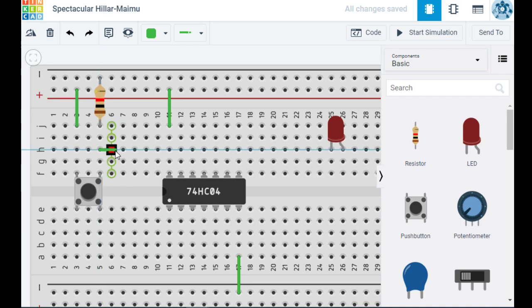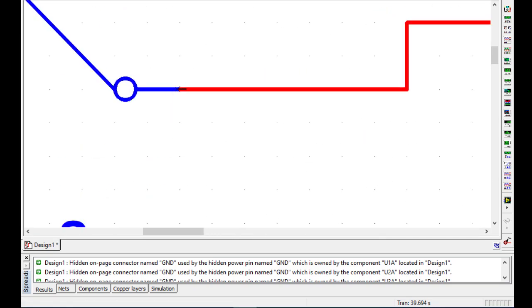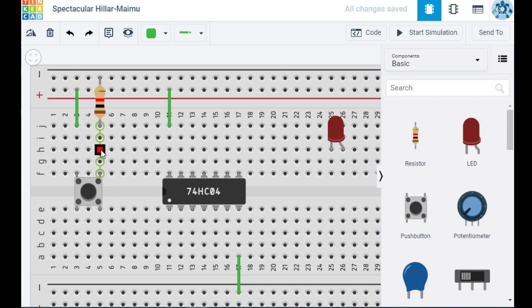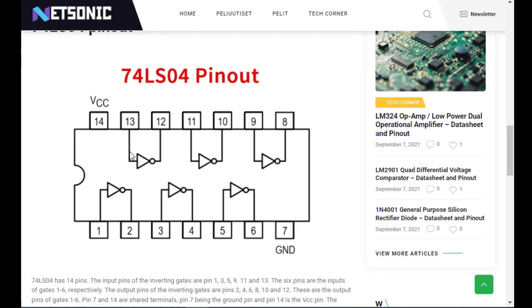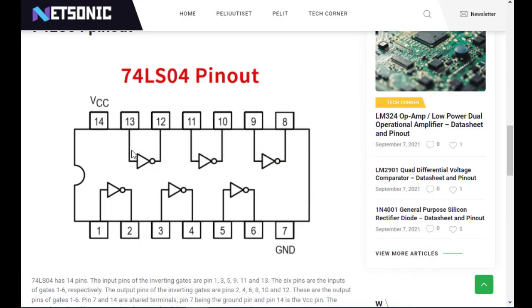This wire right here, so anything in this row, this is where we're going to get our wire for our switch. That would be this part right here. Do you guys see this one wire that comes out of our switch right here? This one? That's this right here, anywhere in this row. So I'm going to take this one wire, and I'm going to run it to there, right here, this row. Why am I running it to that row? Because I'm putting it into my inverter right here. Do you guys see this? I'm putting it in there. And that's what I need to do. If you look at Multisim, I need it to go from there to the input of the inverter.